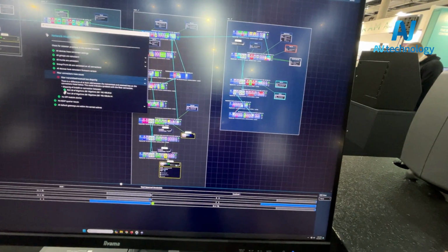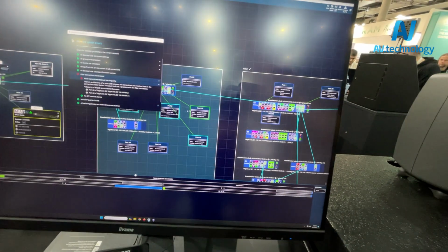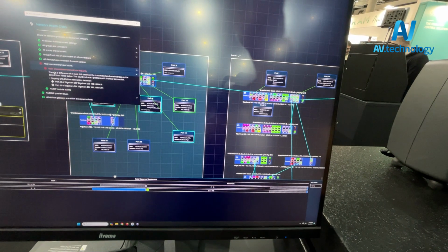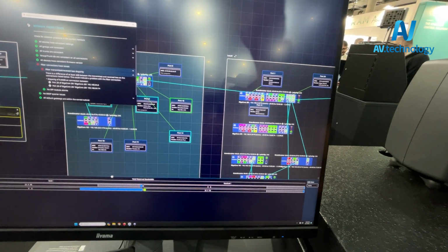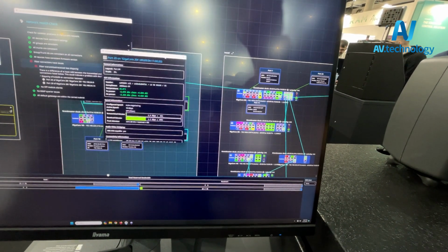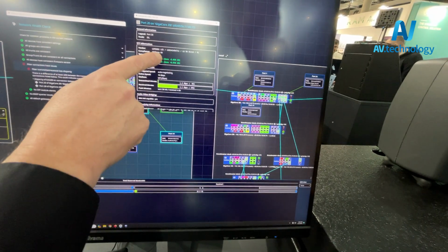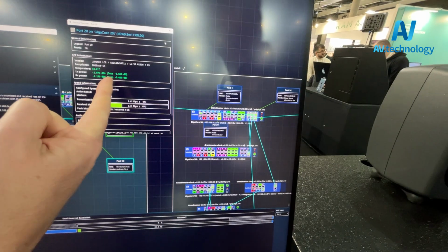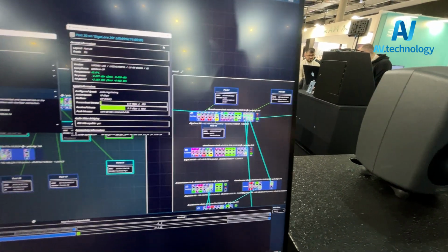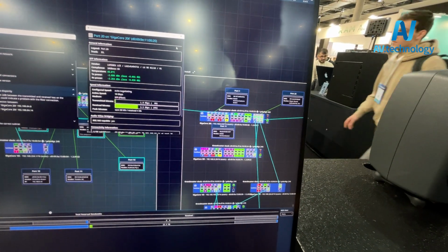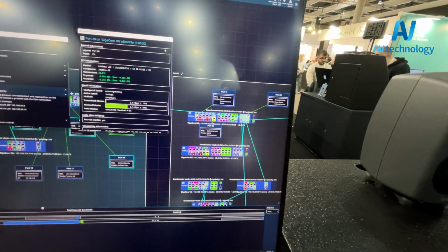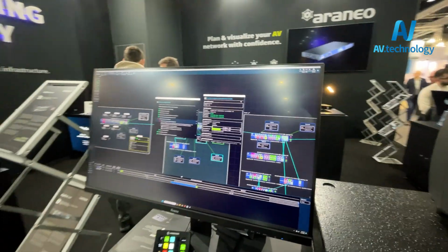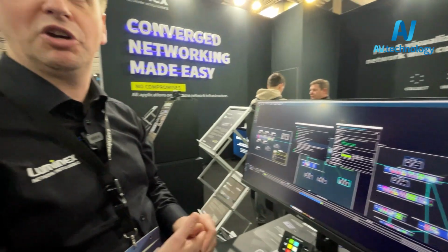It tells me on this port 20 of this switch, there's an issue. Actually, when I look at it, there's a fiber connection. The fiber is 2 strings. On one string there is almost no loss, on the other string there's a big loss. That's a good indication that it's either a dirty fiber or a cracked fiber, so it gives me a warning up front.